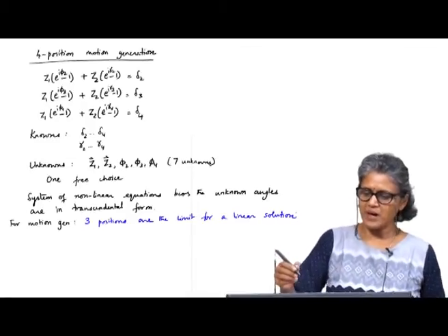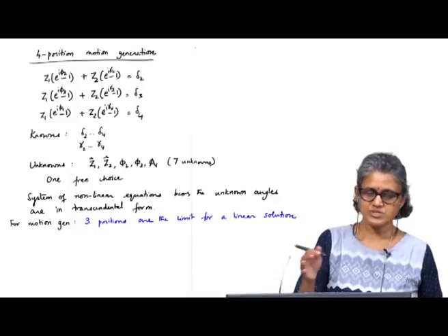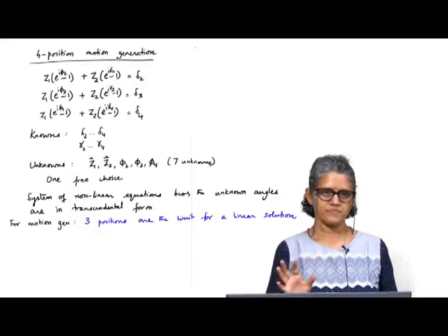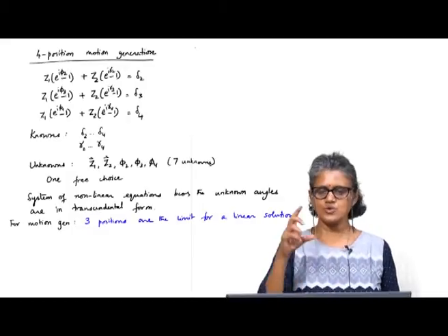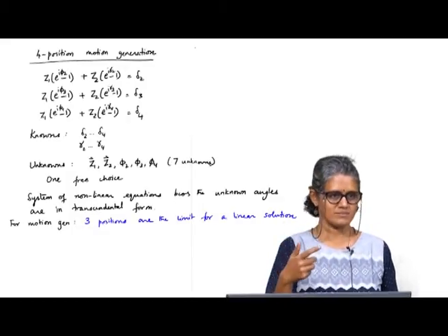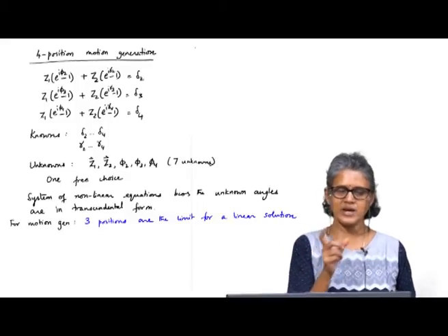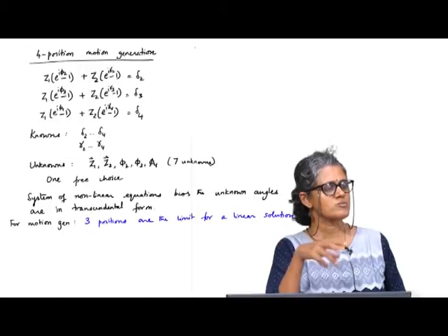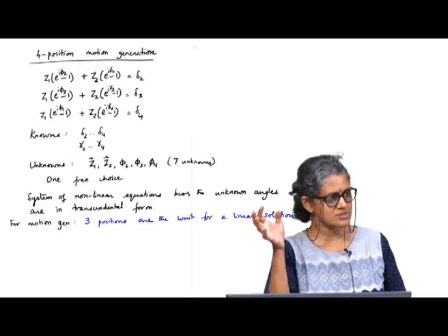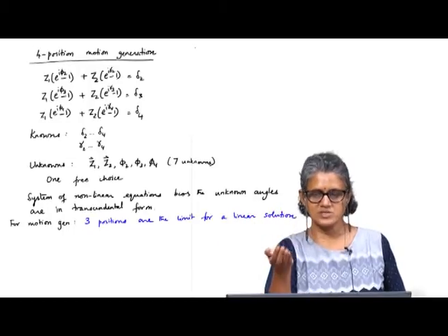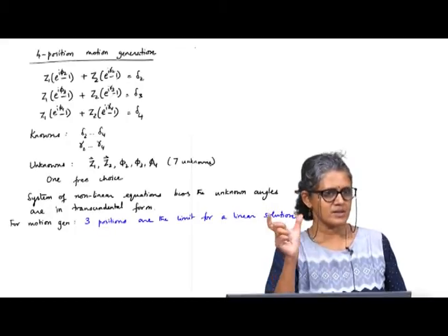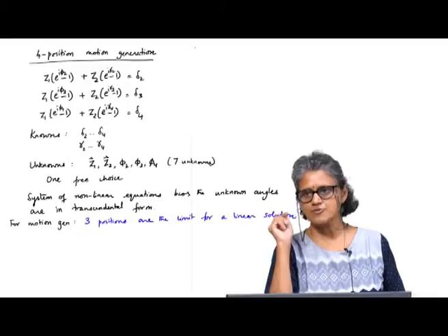So for the 4 bar, once you solve both dyads, you get the coupler. You could have the same routine. Basically, in MATLAB you would write a routine to solve the dyad form for say 2 position or 3 position synthesis. Call the same routine again to solve the right side dyad, and then put together the 4 bar for your solution.